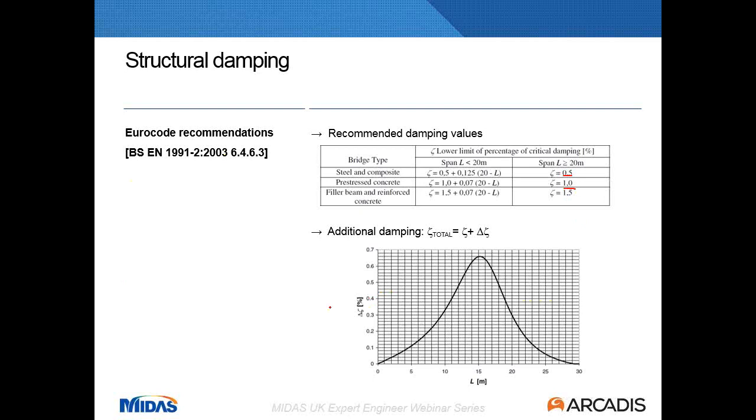My experience is when you are designing a bridge and you don't have any monitoring results of a structure, you will not have values that allow you to differentiate which damping ratio can be applied to mass and which one to stiffness. And the codes give you these values for modal damping. So those are generally the ones that should be used for a new structure.